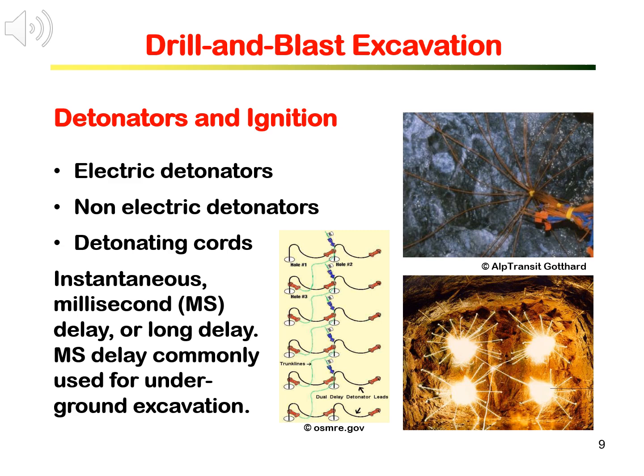Blast can be instantaneous, millisecond delay, or long delay. For underground excavation in rocks, millisecond delay is commonly used.